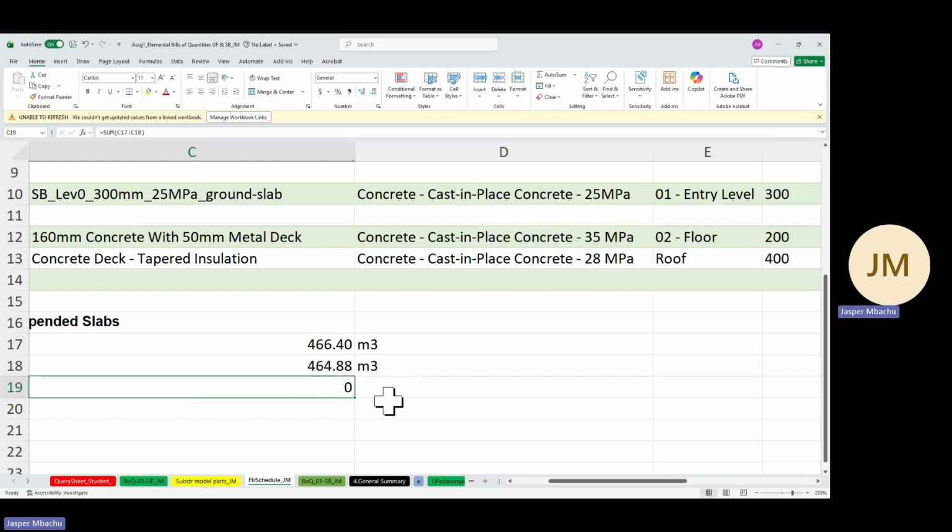It is giving us 0, and that's something I want to tell you now. Whenever you extract any quantity using that get data, it doesn't treat this as your normal Excel. So you always leave 2 rows down and 2 columns away from the table it has provided for you. If you have less than 2 rows, it will still treat it as text because what you have there is not actually Excel. You go and click on the cell that it's sourcing from, it identifies it as a number.